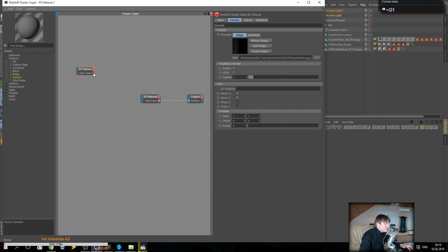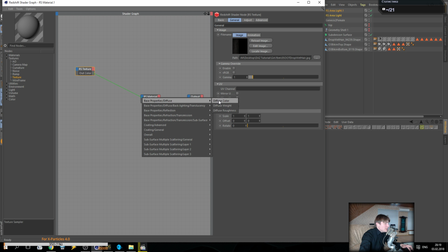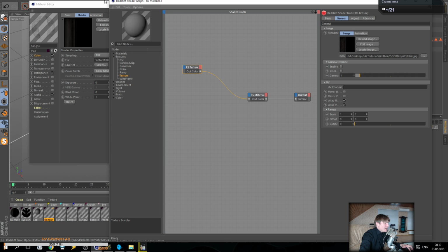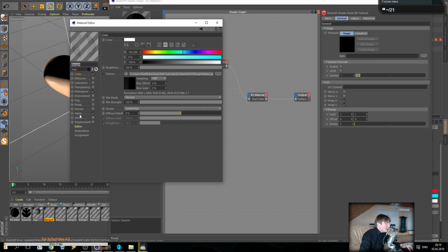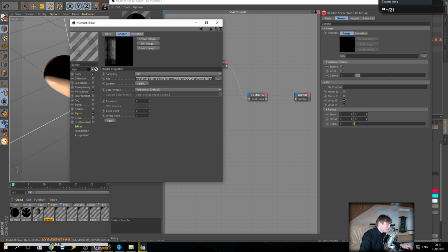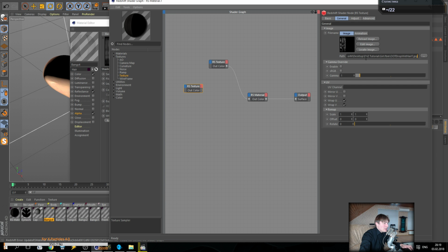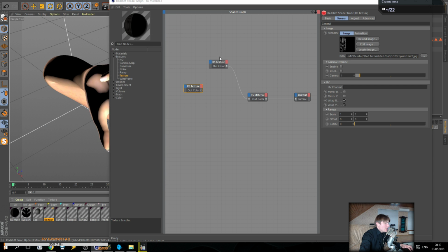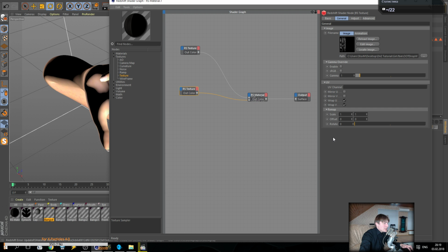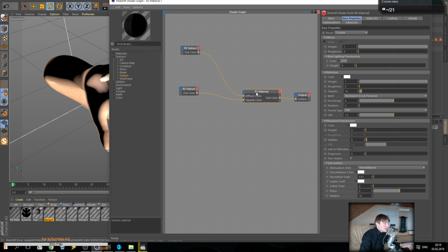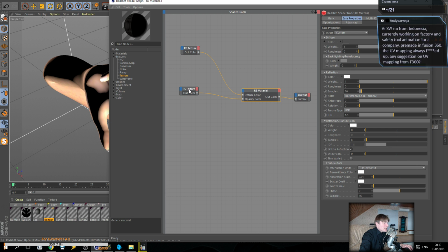Okay, apply it as the diffuse color. Going back to our hair. One more texture, and for this texture we will apply alpha. Copy and apply alpha like this. What next? This alpha, of course, we will use for the overall opacity color. And nothing more. Setup is completed.